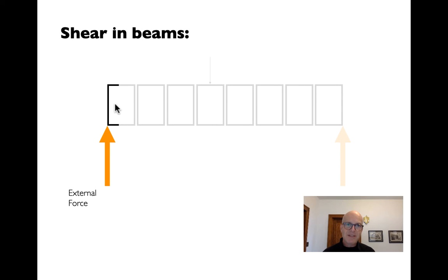And now if we dive into that slice, right, what we find, if we turn this into a free body diagram, ignore the rest of the beam, and think about what has to happen to keep that little slice just to the left of the beam in one position, what we realize is that there has to be an internal stress, right? A force that is within the beam itself, a shear stress that builds up that's going to be equal and opposite to that external force, right? This might be 20 pounds, 100 pounds, 50 kilograms, 300 tons, whatever, pushing up.